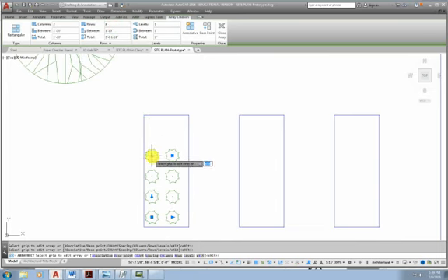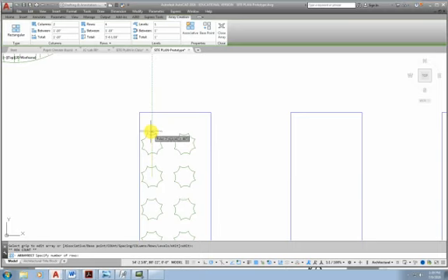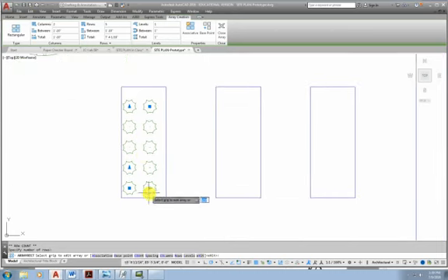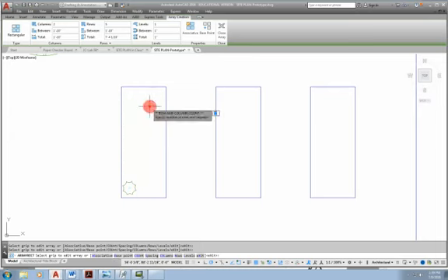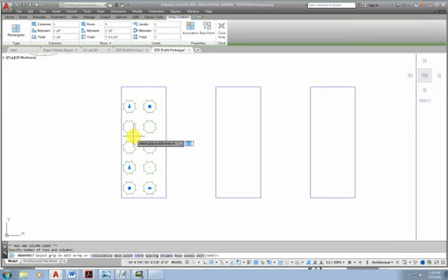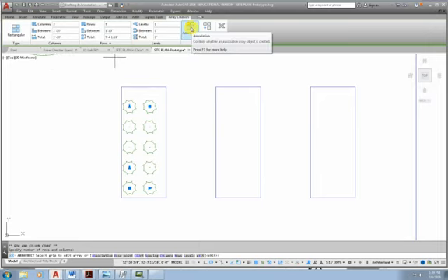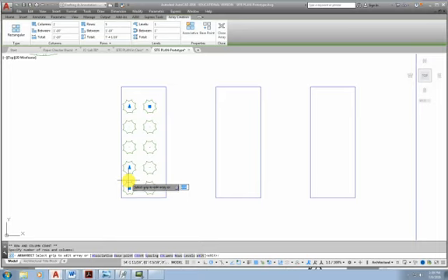Take that, and what's nice about some of the array options in the way AutoCAD is working nowadays is that you can grip them and just pull them where you want them. It's not exactly helping me on it. Maybe if I got that. But we can undo this associativity if we need to, and then they'll treat each one as an individual.